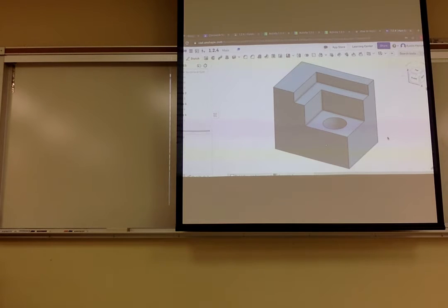Do you remember the shortcut for how to make that drawing that I showed you? So you go on the bottom left and click part. You click it, it'll highlight, it'll confirm this is the part you want. Right-click that, and tell it to create a drawing of that part, right in the middle. Then you're going to click the four view. This is not a blank document, and click OK. Yeah, this standard one is just fine. And it'll place them for you. It knows the standard front, right, top, ISO.